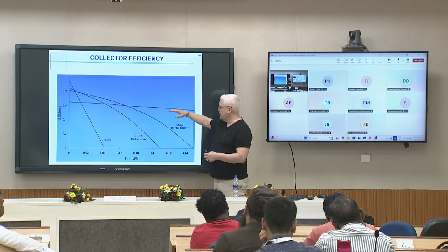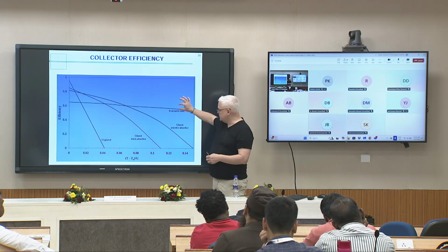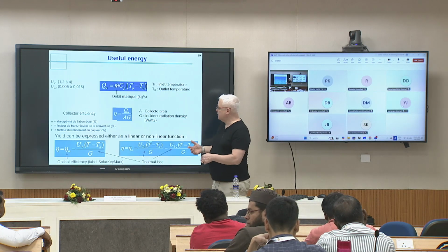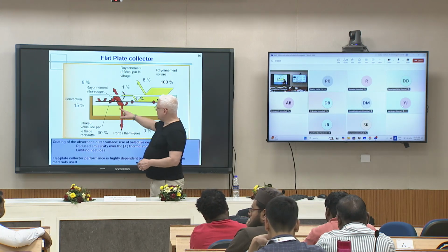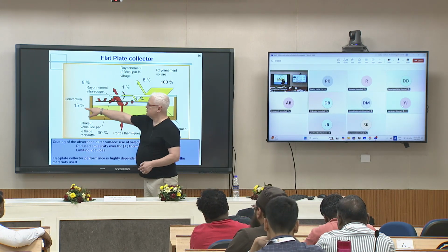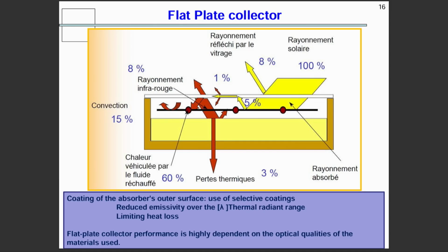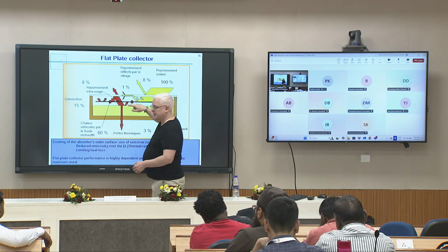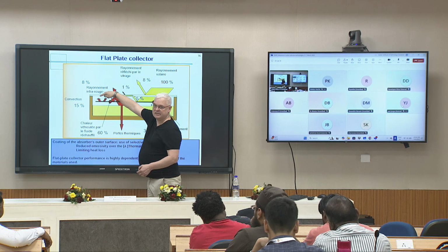Here the thermal losses are negligible because the vacuum tubes erase the convection. In the other case you see convection phenomena because you have air: it's hot here, so you have a circulation of hot air inside that exchanges with this glass and generates thermal loss.